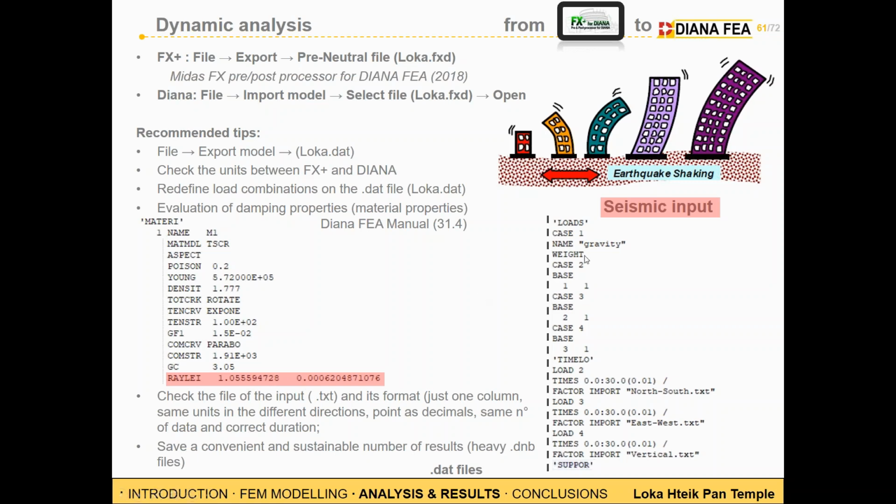And then we can talk about the base excitation load. Base excitation is the option we found before in the graphical interface to apply dynamic inputs to the structure. The first string refers to the load we want to apply, such as base excitation.